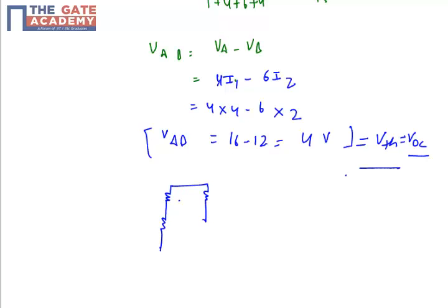We will have a network where the current source is open. So we will have 1 ohm, 4 ohm, 4 ohm, 6 ohm, and you need to calculate the resistance across A and B. The calculation of the resistance is always very simple. Assume one battery here and see the current flow. If current is dividing, it's in parallel. If current is not dividing, it's in series.